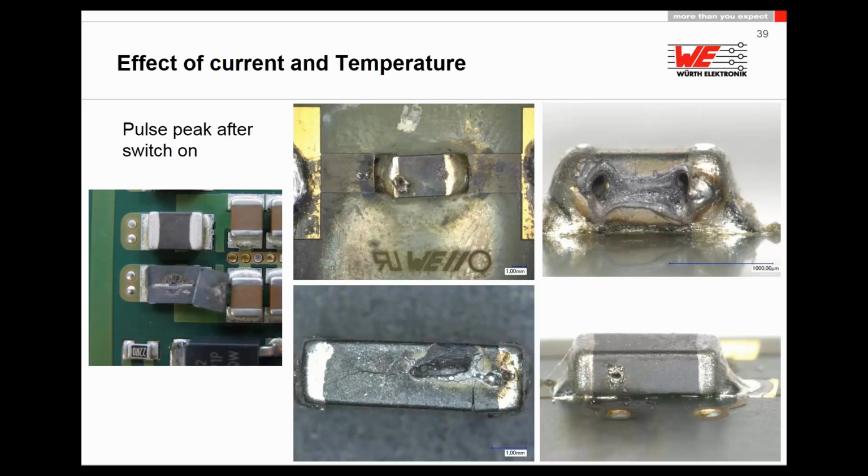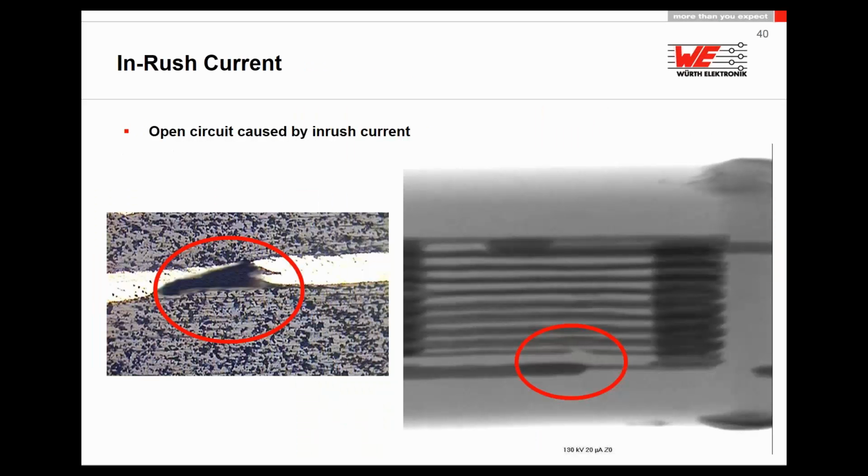What to do now? Well, first, what you can do is put a capacitor in front of the ferrite beads, and this is a nice solution. But if you want a component which can withstand this pulse, then I would say it's better to apply some other components.